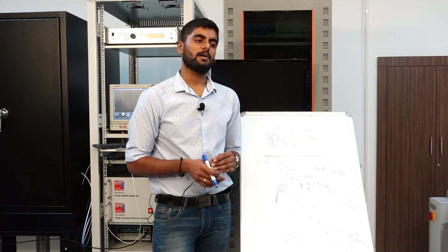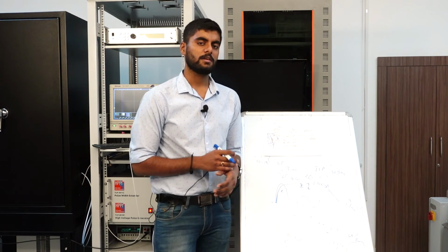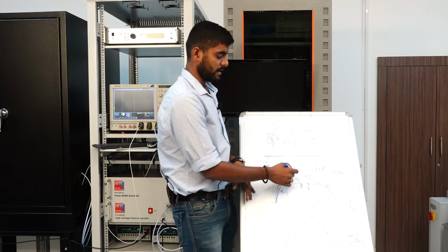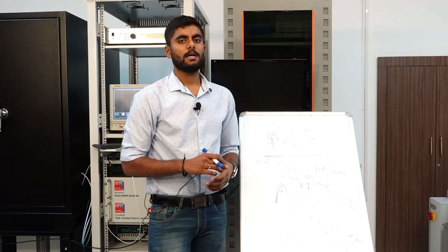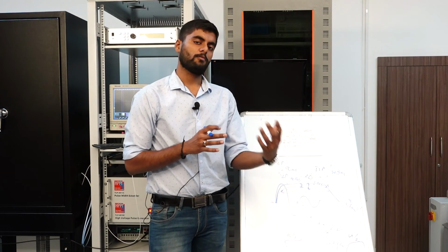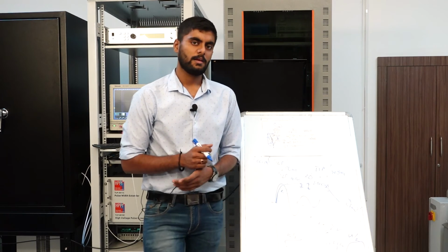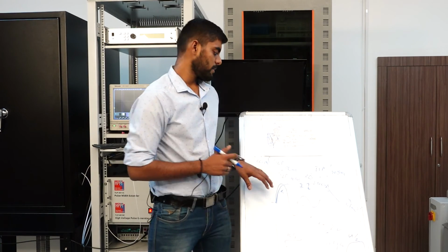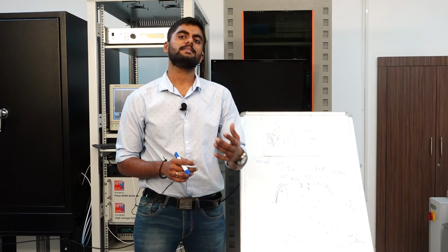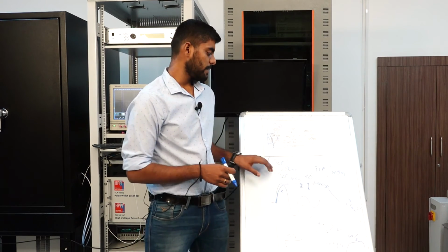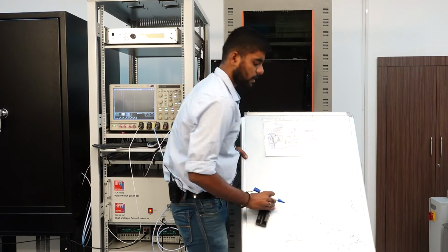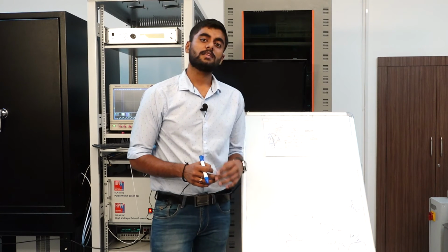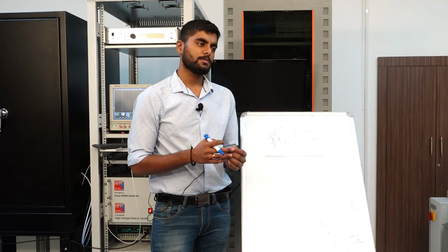The importance of TLP comes into the picture because it gives you a more physical picture of how the device is failing. All these other measurement techniques, CDM, MM and HBM, only give you an ESD qualification vis-a-vis your device under test, and they just tell you whether the device has passed this level of qualification or not. So say for example, if you design a MOSFET which is supposed to stand 2 kilovolts, your HBM and your CDM would only tell you whether the device is passing that level of voltage test or not. Your TLP, on the other hand, because of the voltage signal that you are applying, gives you much more intuitive and physically important information as well. So that's why TLP is preferred in some senses.